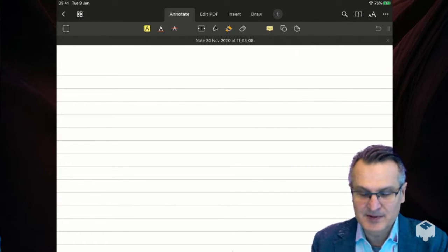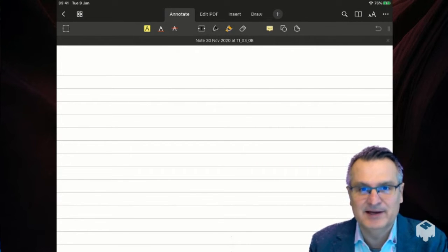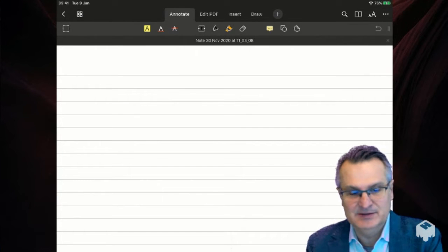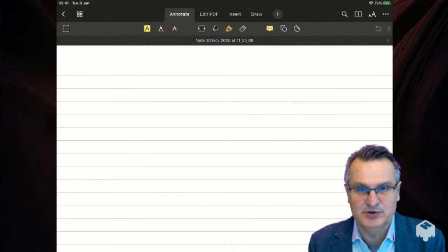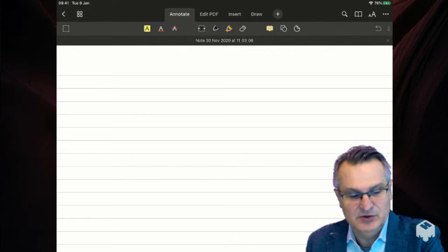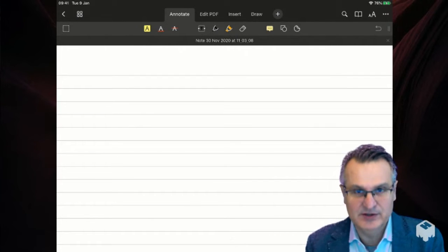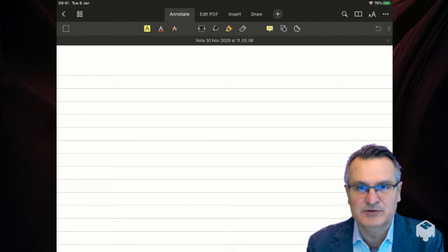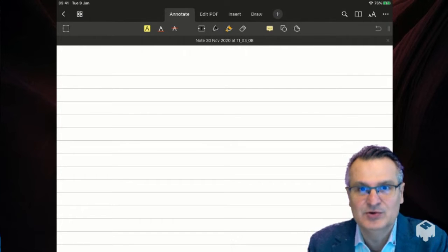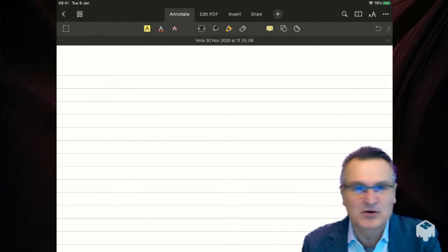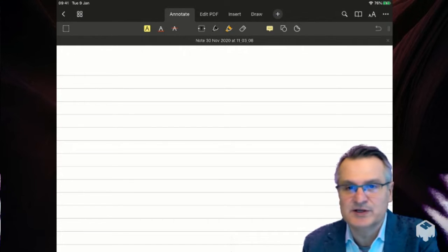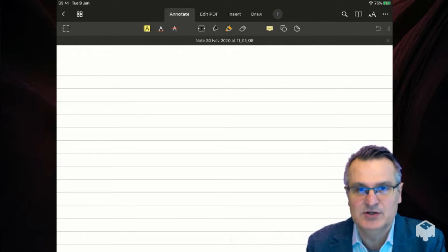So it takes a lot of mathematics to get there and a lot of mechanics, but in the end, it's just a simple curve fitting exercise. And it's not that difficult. If the line is straight, you have to adjust the slope and the ordinate, but if it looks like it's growing exponentially, then I say, let's try an exponential like the Fung material.